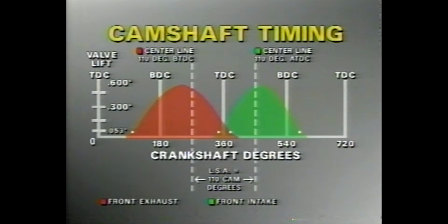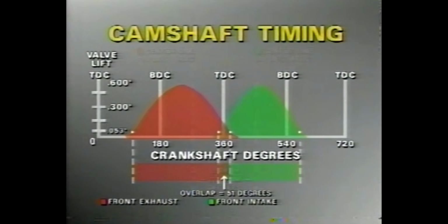Two camshafts may appear to be identical by having the same duration and lift. However, different lobe separation angles will result in different performance, even for identical values of duration. It is the LSA that cam manufacturers use to control the valve overlap and duration, and thereby the power band of their respective camshafts. Making the lobe separation angle smaller without altering our duration will cause the intake valve to open sooner and the exhaust valve to close later, thus increasing valve overlap.